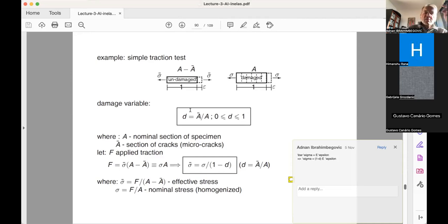So how do we handle this now in computation? Well, you say the ability to resist the imposed load and to have the reaction, whatever force-bearing capacity of this specimen, is basically either I take the nominal stress, which is equal to sigma, and I multiply this with A, which is the nominal cross-section.